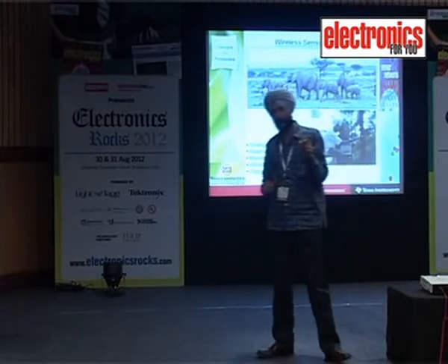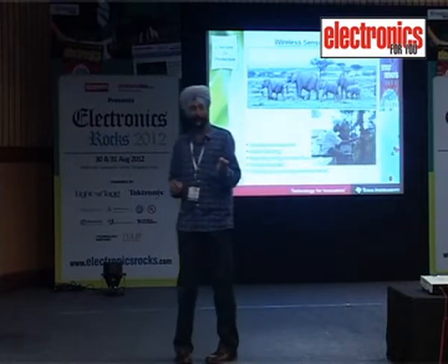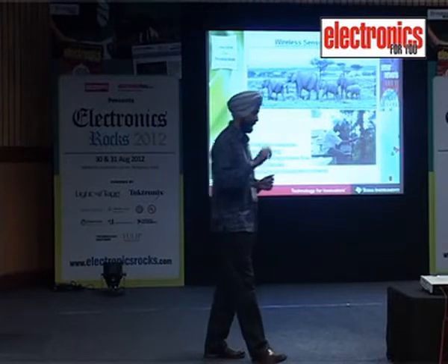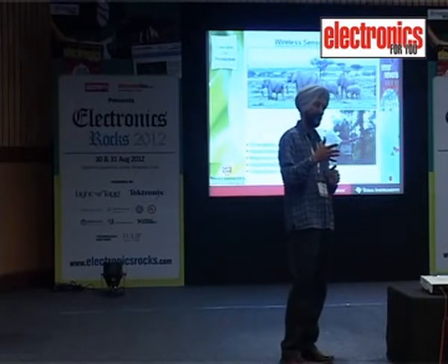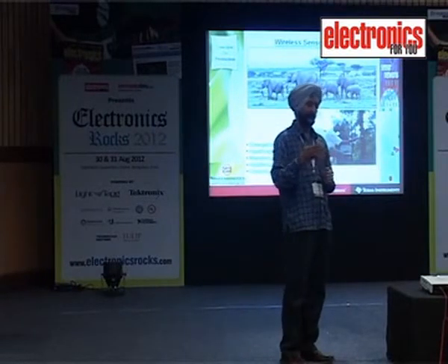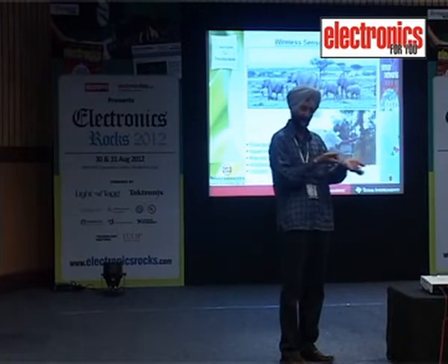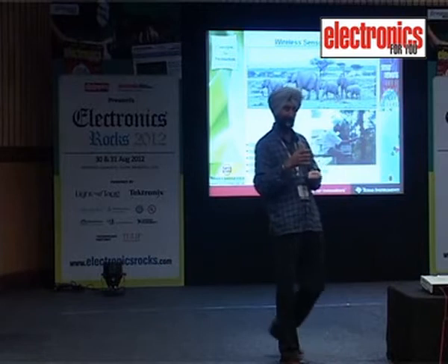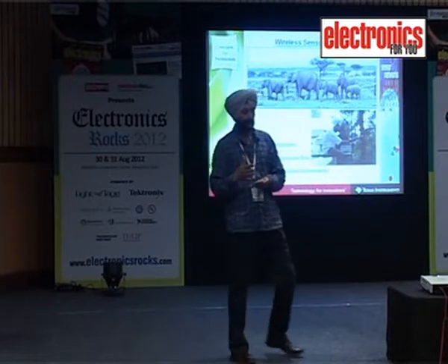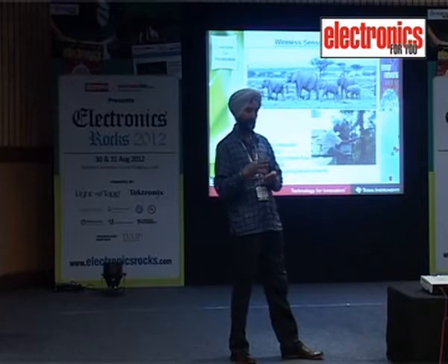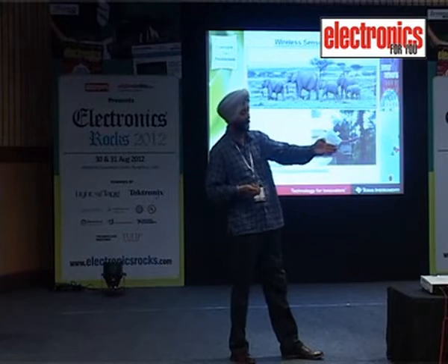Now we need just a $1 device, that is an accelerometer, available from Freescale, since TI is not manufacturing this particular accelerometer. This accelerometer can give you analog output as well as digital output. If it is digital, through SPI or I2C protocol, you can interface with MSP430 and get the streams, with the accelerometer chip in vibration mode. You have two modes: one is acceleration mode and the other is tilt mode. Tilt mode will sense the angle.